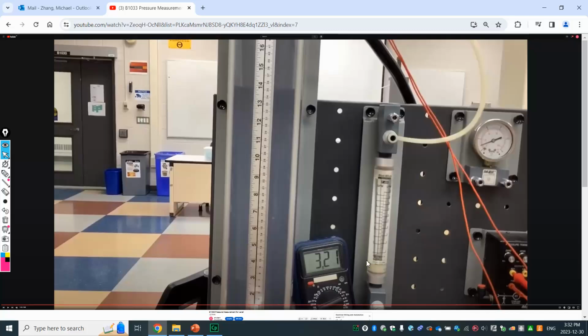One common mistake is that you see the water level drop, but even before it drops to 10 centimeter, around 15 or 17 centimeter, you already see the voltage change to 0 volt. That's not right. You should rotate the zero and span to make the output more accurate.